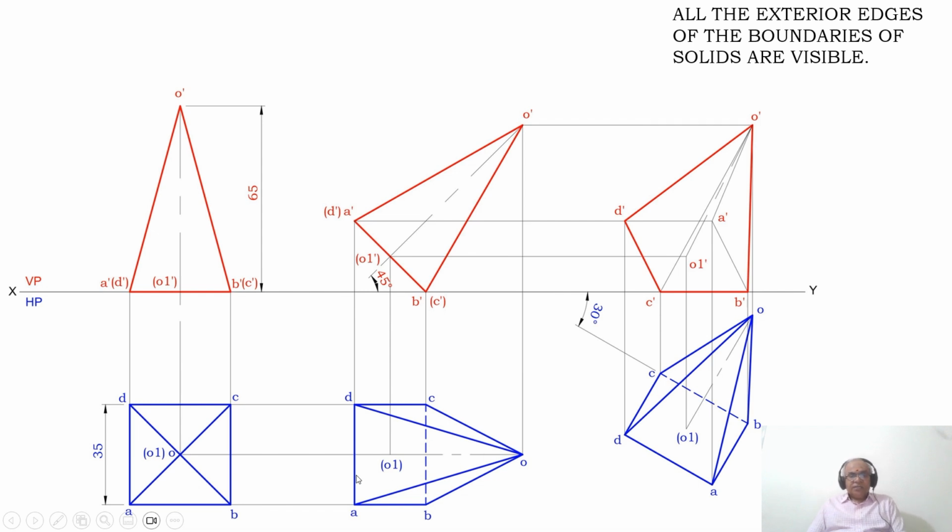As we know, since we are rewriting the same sketch, you draw A to B, B to C, C to D and D to A with dotted lines. Once you do that, you measure the distance from B to this point from the second position top view by using the compass. From B, you cut an arc on this dotted line.